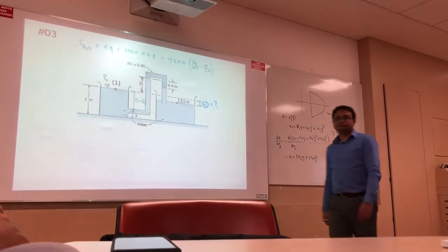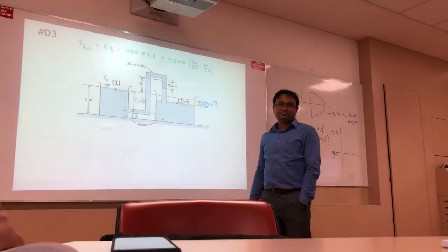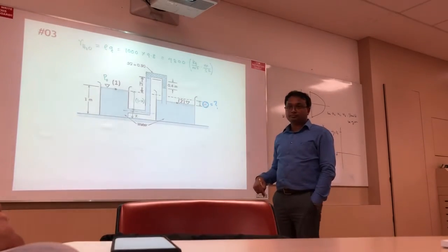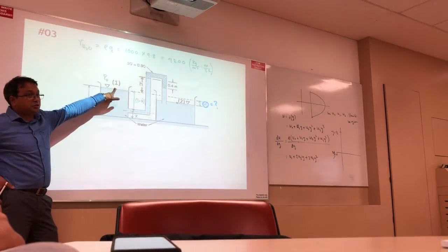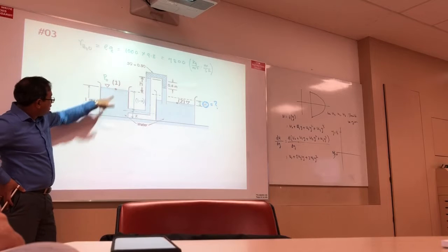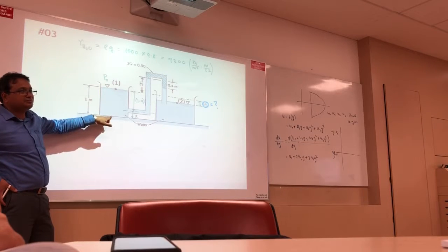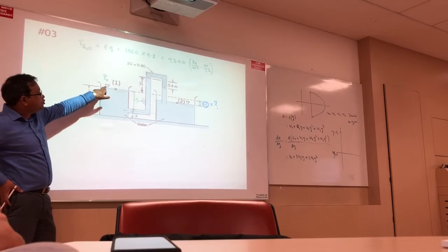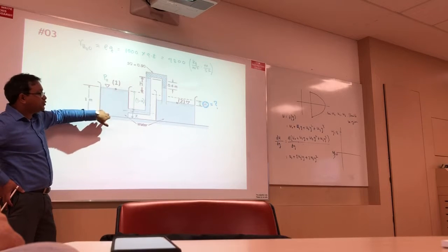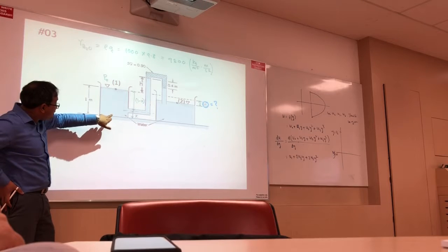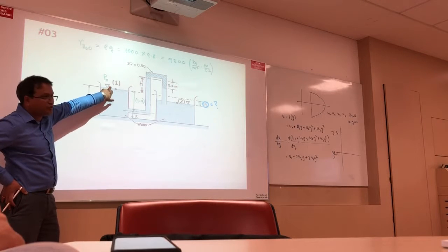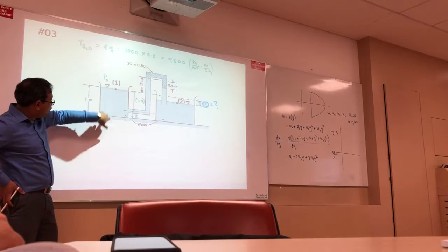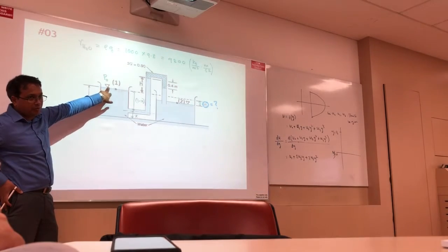How? How can you solve this? I show you here two methods. Okay. At that point, what is the pressure? Atmospheric pressure, right? Definitely. At that point, rho G H. Very good. From here to here is rho G H. And from here to here, minus rho G H, right? Correct. So rho G H minus rho G H is 0. I come back here. So first I go here, then come back here. Same thing, right? No problem.